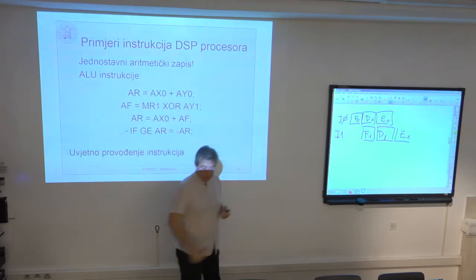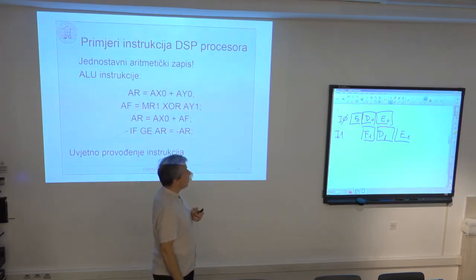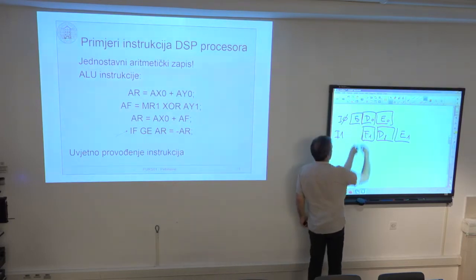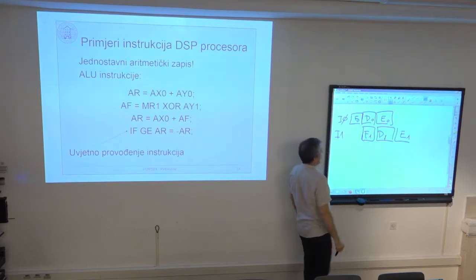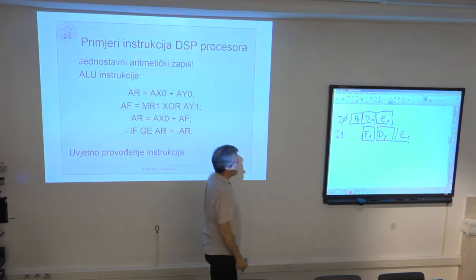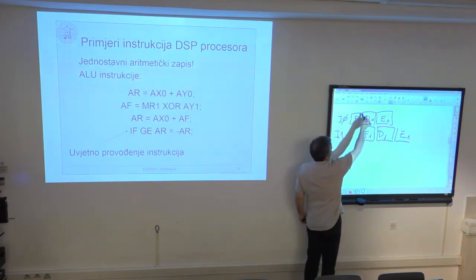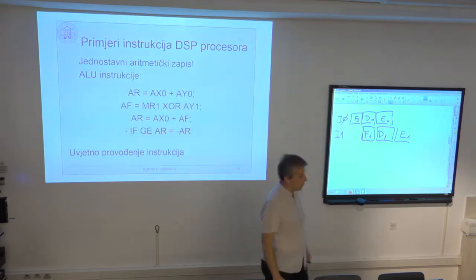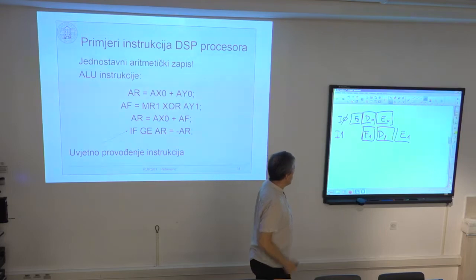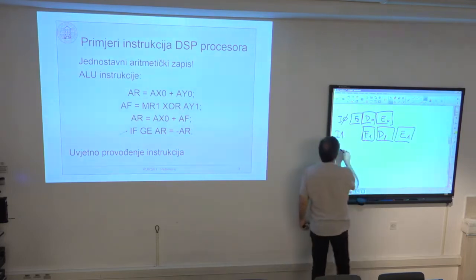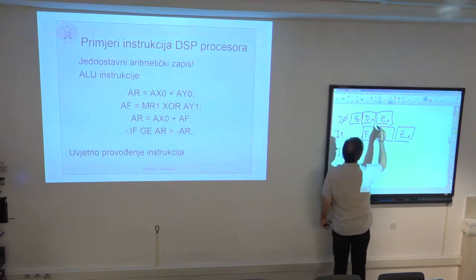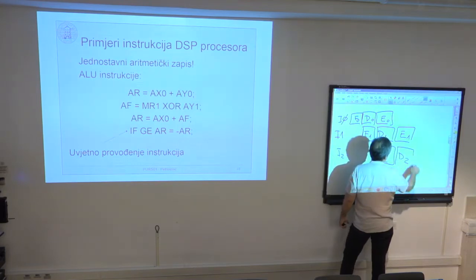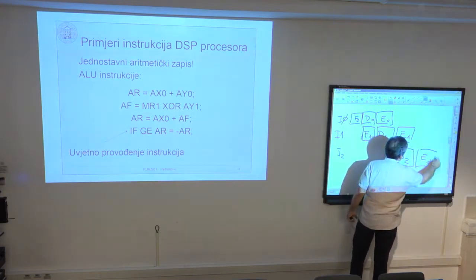So there is no interdependence between these two instructions. The idea is I would immediately start fetching the next instruction from the program memory as soon as instruction 0 is fetched, because that instruction is placed into the instruction register and is being decoded by the decoder unit of the CPU architecture. Then the same is with instruction 2. I have fetch 2, decode 2, and finally execute 2.